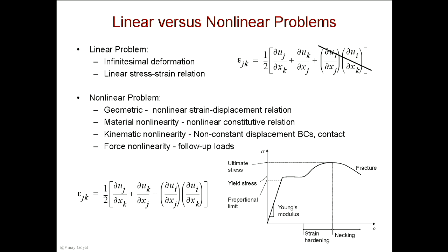Can you repeat that part where you say you have really high stress? Yeah, if you run a linear analysis and there's a stress concentration in the model, if you can write positive margins for that structure with a linear analysis, you're probably going to be okay.